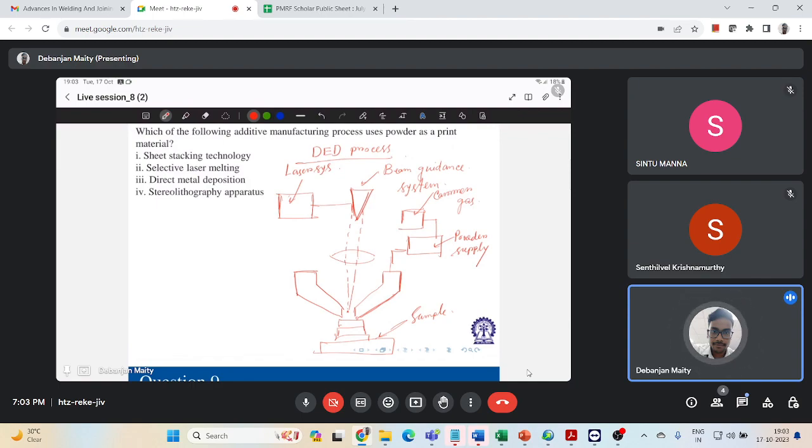This process can also be used with conventional manufacturing processes for finishing and machining. The process is mainly used for aerospace applications due to its dimensional freedom, so there is no size constraint in DED. The materials used in these systems include titanium, Inconel, SS and more, and industry is working on establishing this DED process for different kinds of materials.